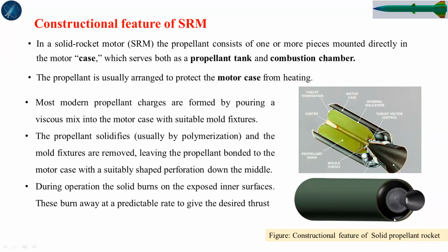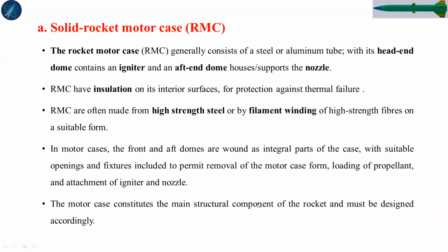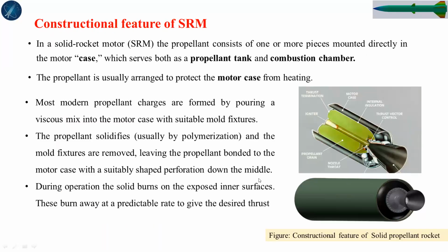This dome supports the nozzle so it does not come out because of the high thrust force or the high speed ejection of burned propellant mass. This is the aft dome, and this is the forward dome, also a dome here, the front dome. So this should be under consideration.